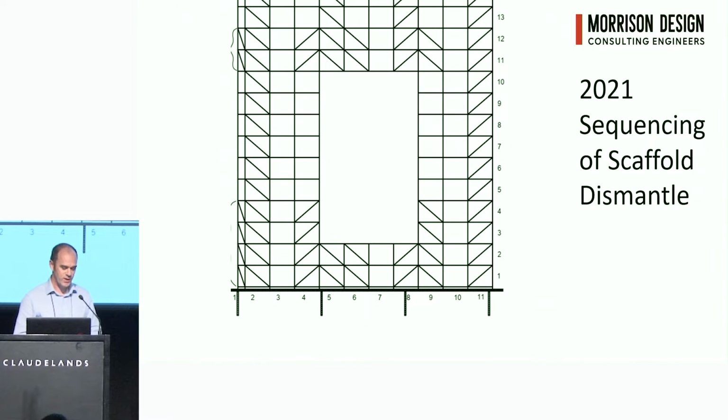You may have some situations where you've essentially eroded half of that truss that's spanning between the brackets. So it's worth confirming with the scaffold firm their dismantle sequence particularly, and their construction sequence that they're intending to use.